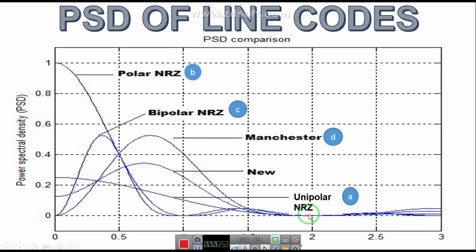Almost twice FB. So 95% of power it is going to transmit. But look at the screen, if the cutoff frequency is reduced from 2F to 1F, then only 70% of the power would be passed. But over here the bandwidth requirement is twice of F, which is double the bandwidth of the NRZ signal.